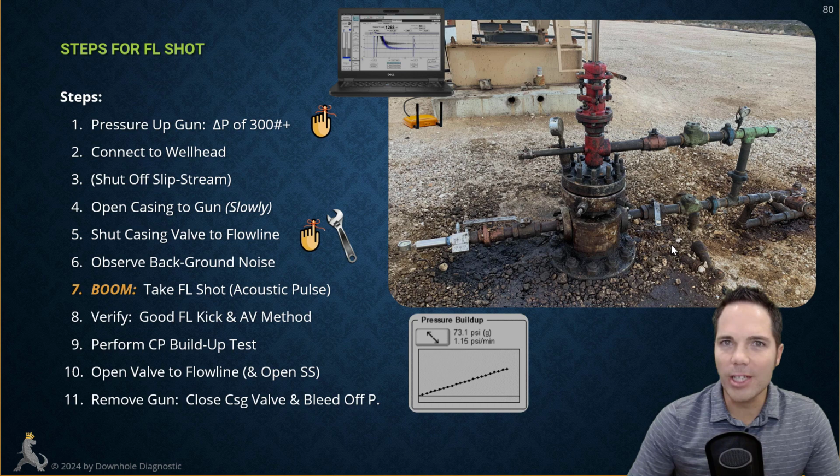Just to make sure that if I go to the next location and I don't have my crescent wrench, well, that's because I left it right here by the closed valve and I did not open this valve up. So even if it has a handle, like this one does right here, I'll still put my crescent so I don't forget. But it's not uncommon that people accidentally leave these closed, and if you do, they're going to build to a very high pressure, and somebody's going to get mad at you for doing that. So don't forget to open this back up when you're done with the test.